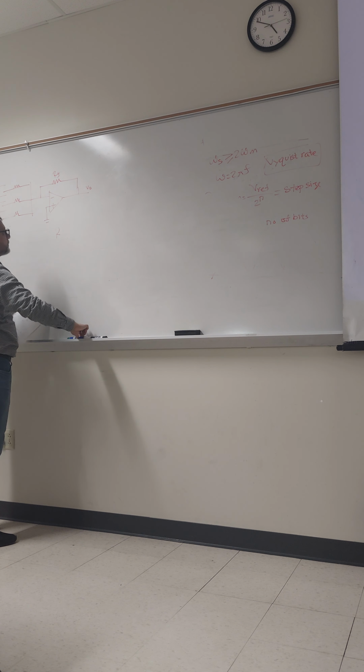I have a question. Yes, please. I studied in the basics about voltage gain and loss. The thing is, we're getting a negative output, right? The negative means only a phase shift, only the phase. If we put an inverter, then we can get the positive output. Or instead of this one, if you give the input to the positive terminal of the op amp, it will give you the same phase. Okay. Yes.